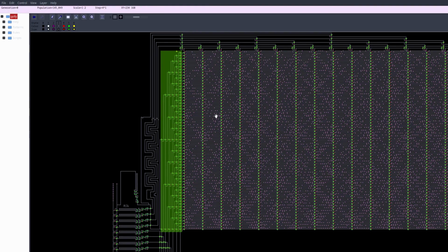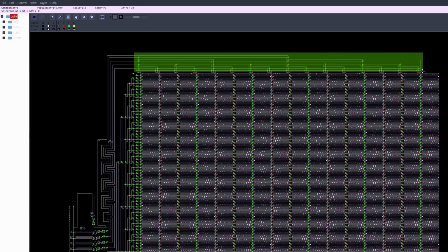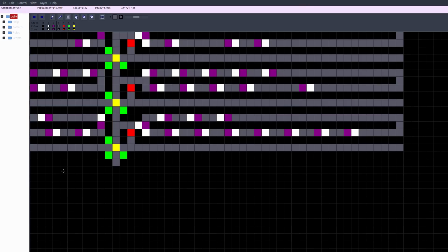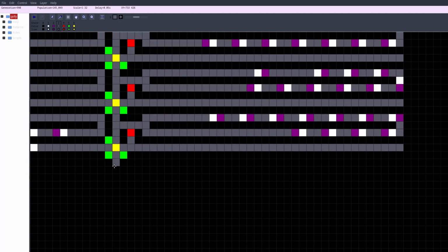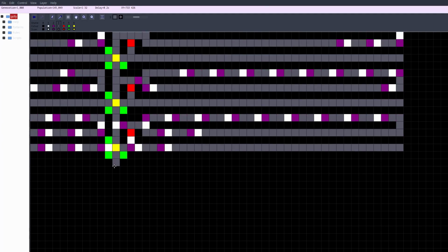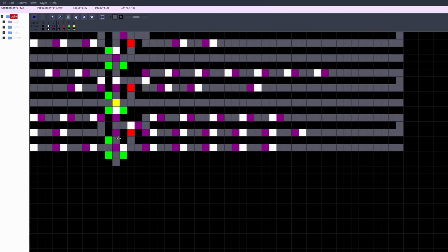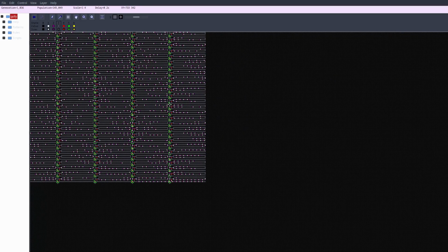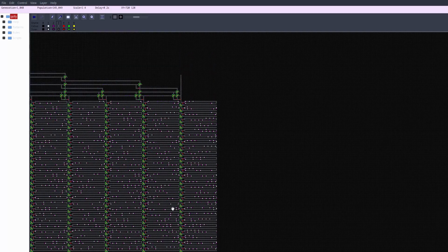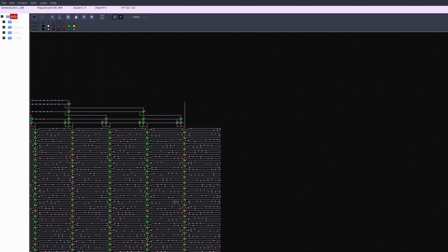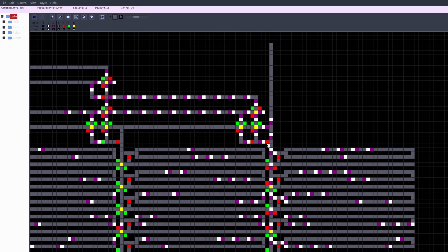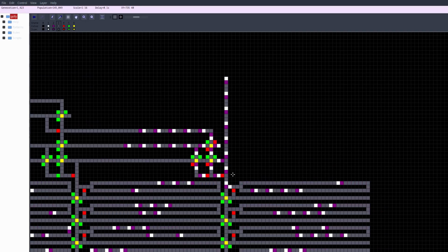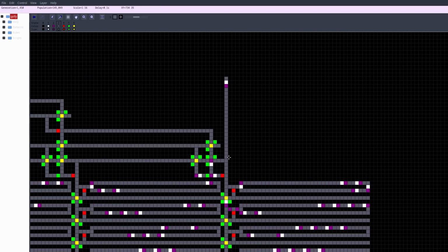These, along the side and top of the ROM, are the demultiplexers, which select the row and column of the desired instruction. Here is the currently selected instruction. The read signal arriving from the vertical demux on the left reads all 18 bits of each instruction in its row. These signals then travel upwards, where the horizontal demux selects one of the columns. Here it's filtering out the others and selecting the one we want. This is the 18-bit output of the instruction at the specified address.